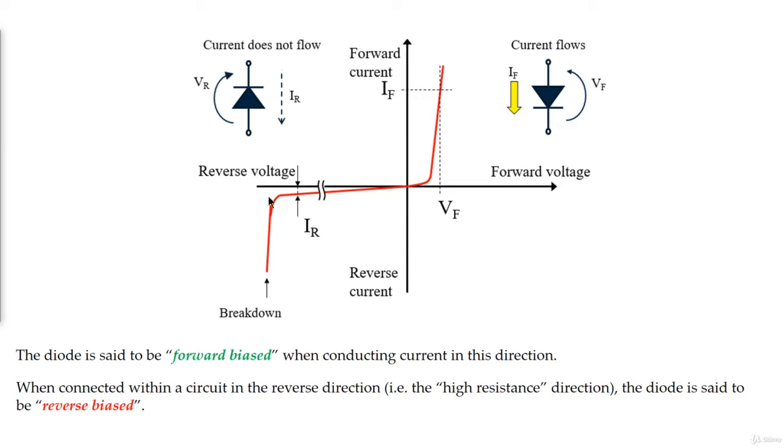in the reverse direction. I know I said that a diode can conduct current in only one direction, and this graph just shows the opposite. But what you have to know is that this reverse breakdown voltage is usually very high compared to the forward threshold voltage, so it's much harder to conduct electricity in this reverse direction than in the forward direction. And this is why in practice we say diodes have a high resistance in the reverse direction and, well, not an infinite resistance.